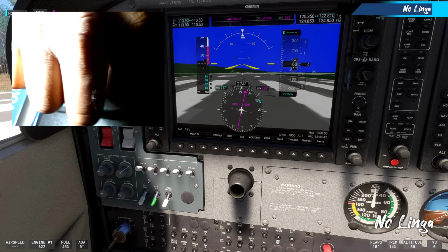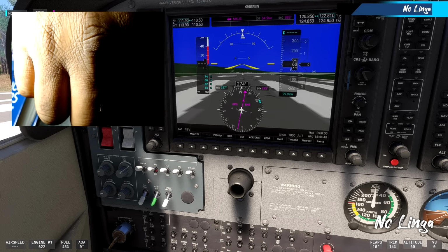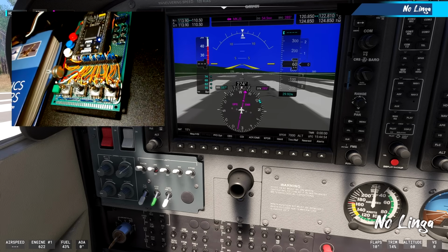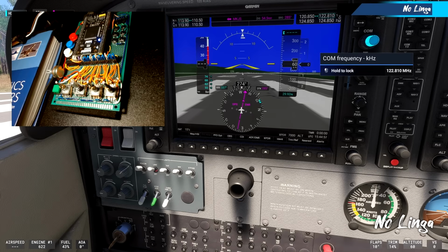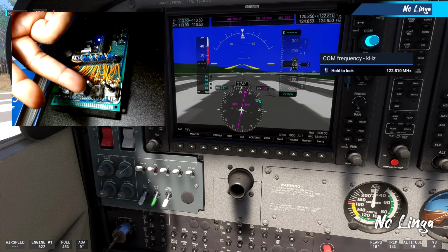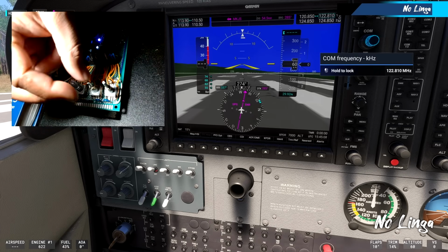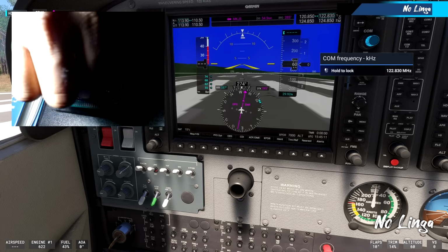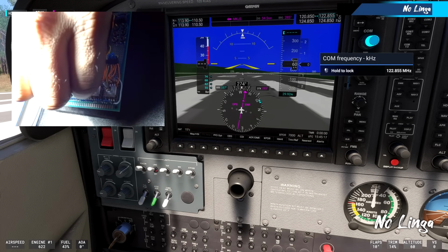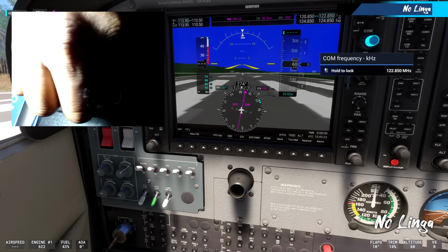And go back there, and I'm changing the nav frequency, the whole numbers. So I get back up, and if you look over on the right hand side, on the comm side, I reassigned that to this top, and then the bottom knob to the second encoder channel. So as I turn the top, you can see the frequencies changing. Let's go up to 50. And then the whole number frequency I can change here as well.